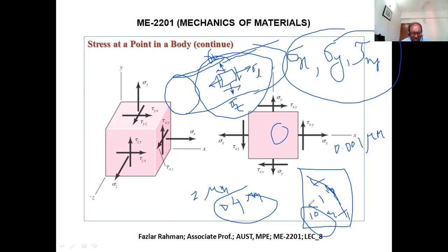What they found was that at launch, the vehicle is going upward, and they put multiple cameras inside and outside. They figured out that in the space shuttle there is an engine at the backside, and there are tiles, heating insulation, and these tiles got off from the surface, hitting this surface, and causing a minor crack.